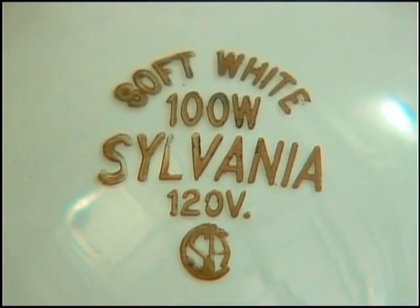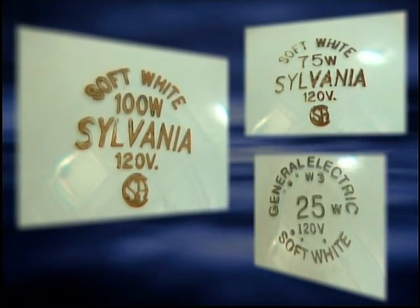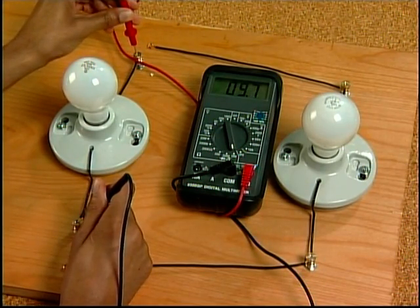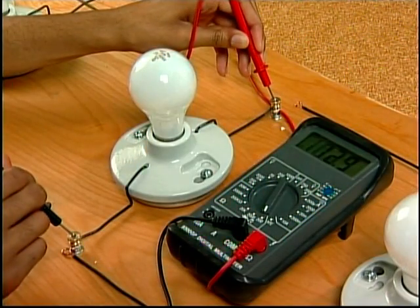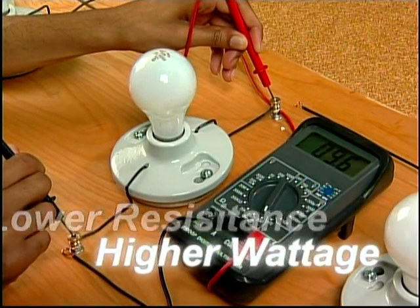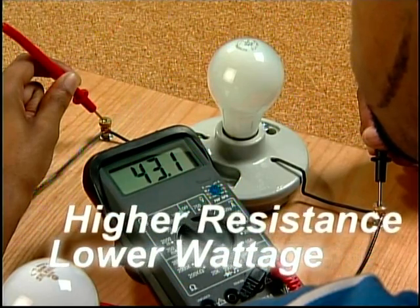This means that a 100-watt lamp will draw more current than the 75-watt and 25-watt lamp and will produce a greater light output. To do this, the 100-watt lamp must have a lower resistance than the 25-watt lamp. The wattage and light output depends on the resistance of the lamp. The lower the resistance, the higher the rated wattage, and the higher the resistance, the lower the rated wattage.